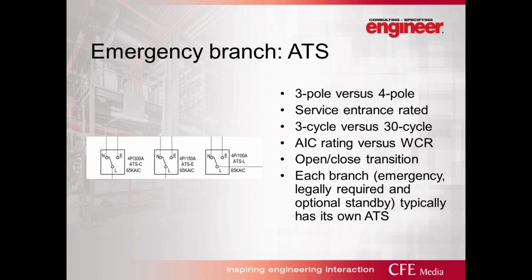The transfer switches are not rated to clear faults. Therefore, they do not have an AC rating. Per UL 1008, the transfer switches must withstand the fault current and also close on the fault current. The transfer switches will have a withstand and closing rating. Each branch typically has its own ATS, referred to in Article 700 through 702 in NFPA 70.